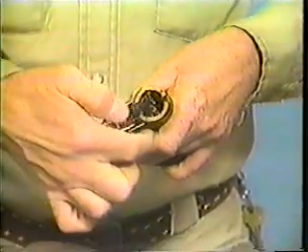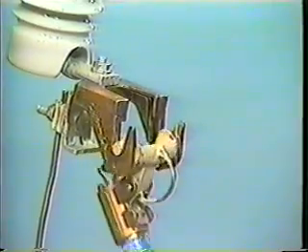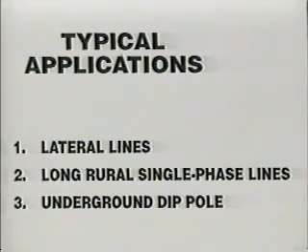When the CES operates, isolation is achieved by releasing a latch in the lower trunnion section of the module. A built-in current transformer provides power to an actuator, which releases the latch trunnion. This causes the module to swing down and drop open, similar to the action of a fuse tube. The open position gives a visual indication of the general location of the permanent fault.